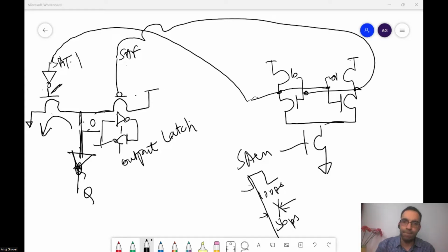Sir, making this common centroid layout is optional, right? No, it is not optional. It was written as study, so do we have to make it in the centroid one? Yes, study the incremental benefit, so you have to make common centroid. You have to make 3 layouts over here. One layout is a regular layout without any matching constraints. Another is a layout with common centroid matching constraints. Third is common centroid plus structural matching.